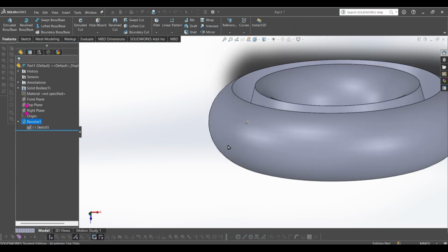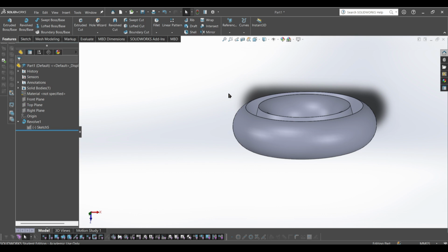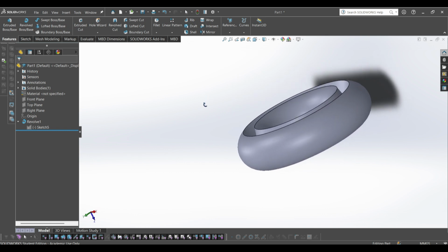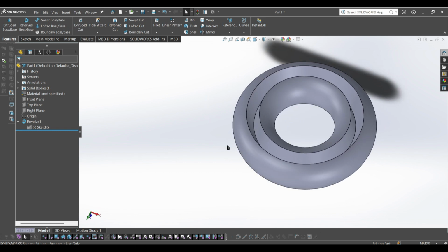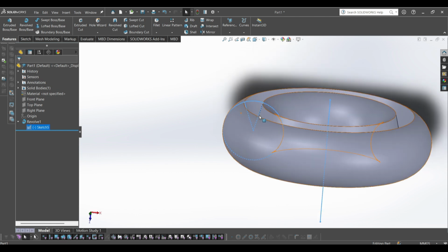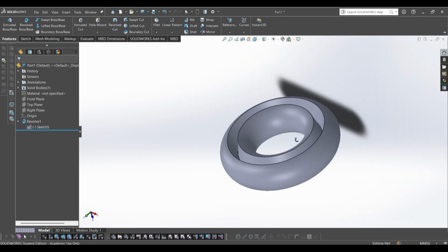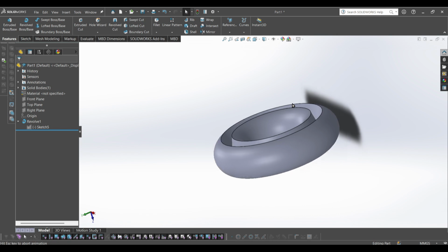And when you're CADing in FTC, you want to use as few features as possible because the more features you use, the harder it is to change one thing and not have it affect multiple things. So if you can do something like this, you should, because it makes your life a lot easier 99% of the time.